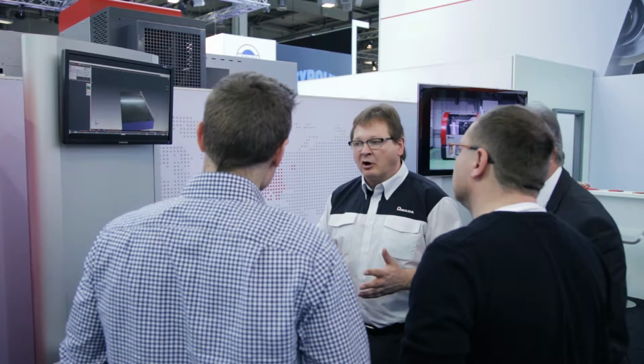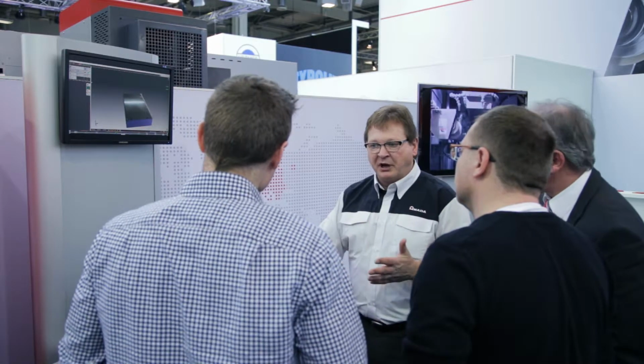CGS software is a software for making programs on all AMADA surface grinding machines. You can use it as a complete programming system for grinding cycles, complex grinding cycles with multi-work systems. So you can combine surface grinding, plunge grinding, face grinding, creep feed grinding. You can combine this and make complex programs.